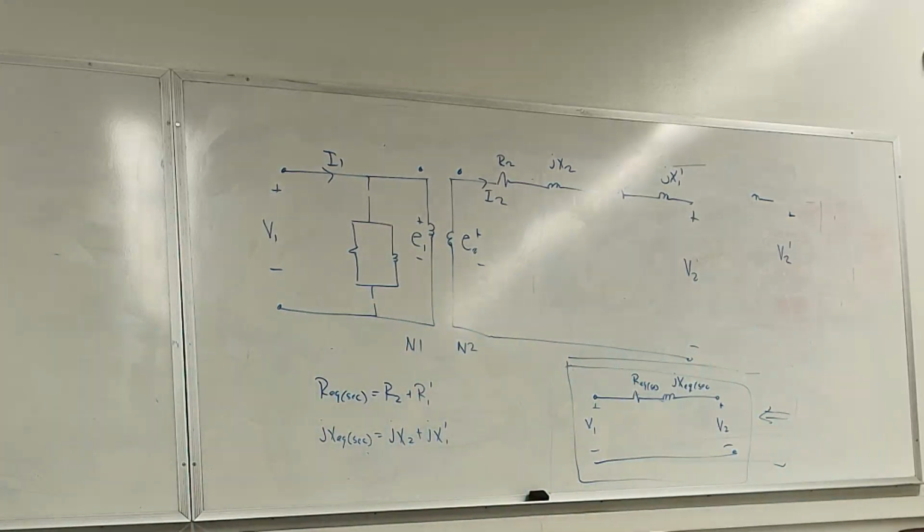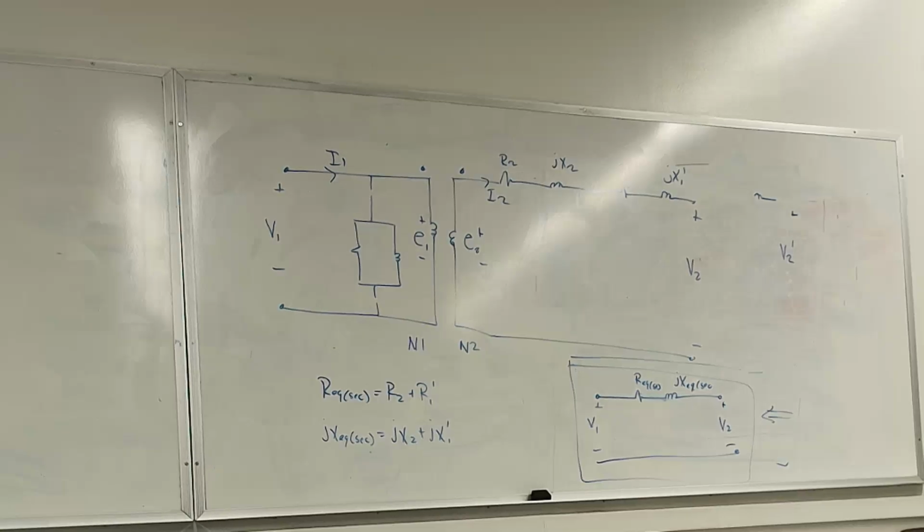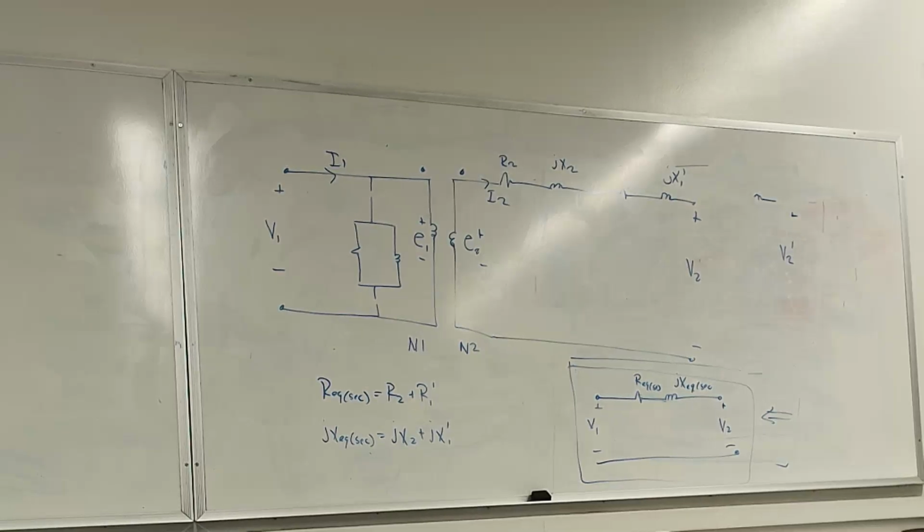So for the most part, and I'm not saying always, most examples that you come across are usually done on the primary side of the transformer. Because you want to transfer everything to one voltage level, assuming that you're dealing with step-down transformers. Different would be if you're dealing with a step-up transformer, then you might have to use the secondary side.